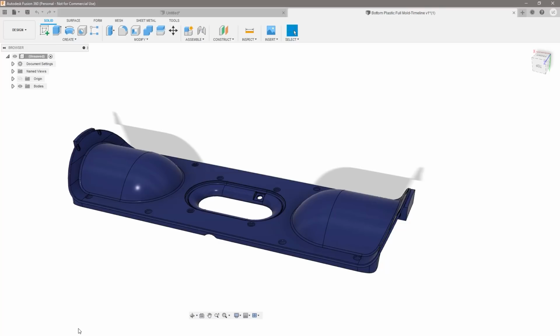Now, the reason for that is that if you're bringing in some part from another piece of software, this plastic part here, where we need to create a plastic injection mold, for example, then we might need to do some edits to this part, and we can use the direct editing tools inside of Fusion and make some changes without having to record all those steps in the timeline. Mainly because the timeline down here can, as many of you maybe have noticed, get a little long.